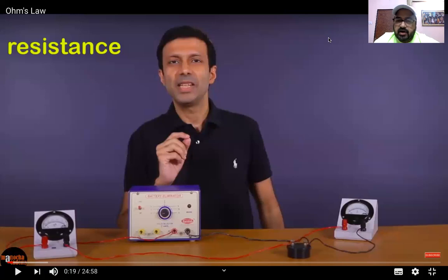ओके, और यहां से फिर आपको एक नया टर्म मिलेगा जिसको हम बोलेंगे रेजिस्टिविटी, और इसी का दूसरा नाम बोलेंगे स्पेसिफिक रेजिस्टेंस. रेजिस्टेंस हर एक सब्सटेंस में होता है लेकिन कम ज्यादा हो सकता है due to their length, area. लेकिन जो वर्ड मैंने अभी बोला स्पेसिफिक रेजिस्टेंस, जिसका दूसरा नाम होगा रेजिस्टिविटी, वो पर्टिकुलर मटेरियल का कभी नहीं बदलेगा. यानी कि 1 मीटर का कॉपर वायर लो और 1000 मीटर का कॉपर वायर लो, in both the cases resistivity will remain same. एक 5 मिलीमीटर थिकनेस का लूं और एक 50 मिलीमीटर थिकनेस का लूं, ओके, तो भी उसकी रेजिस्टिविटी सेम रहेगी. क्या बदलेगा? बदलेगा रेजिस्टेंस. तो रेजिस्टिविटी या स्पेसिफिक रेजिस्टेंस की डिपेंडेंसी किस पे होगी?